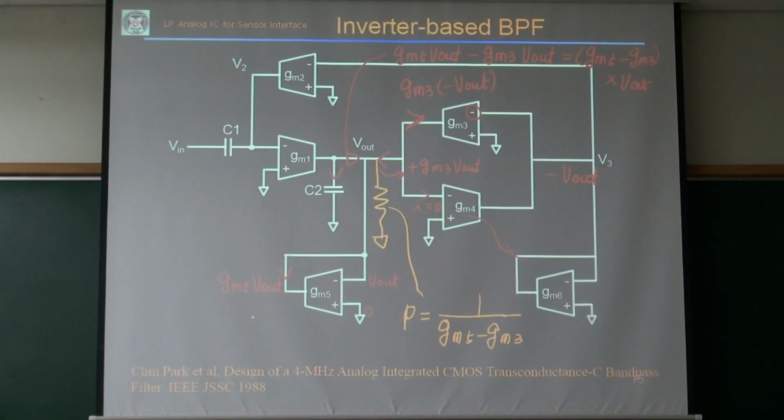So the effect of this inverter, with input and output connected, and this feedback inverter is just this one, right? You can adjust. If you derive the transfer function from here to here, you will see it is a band pass filter.